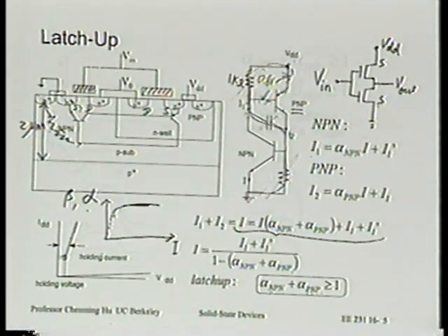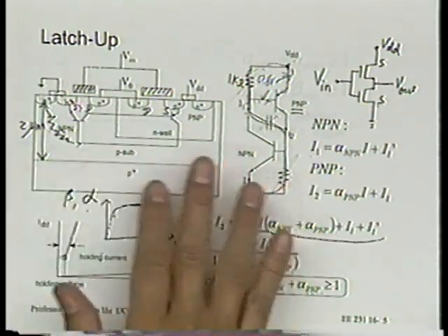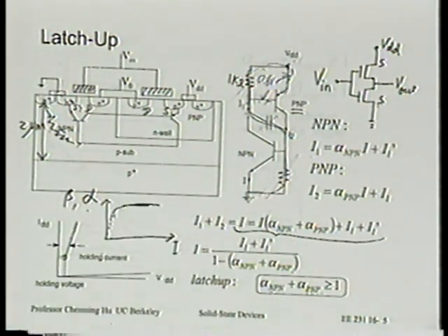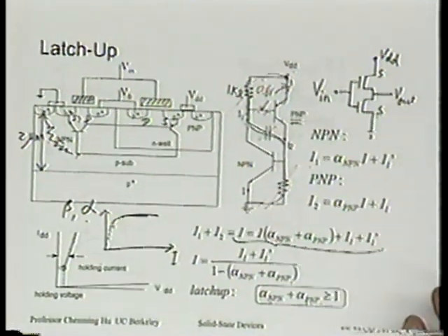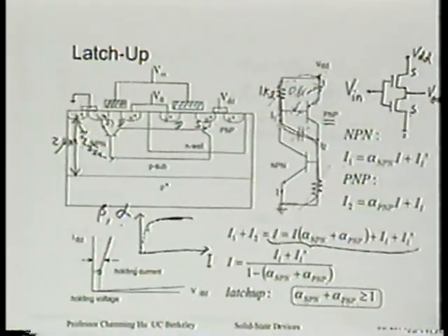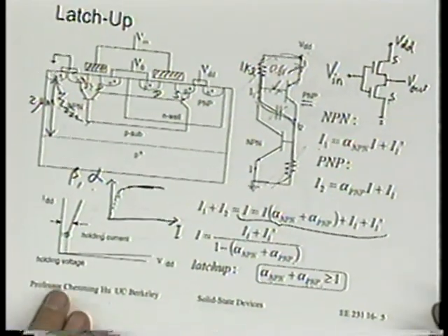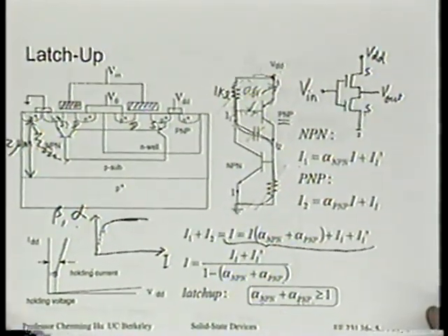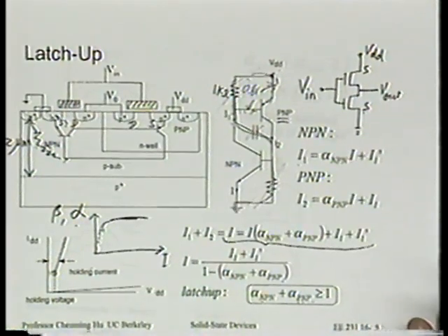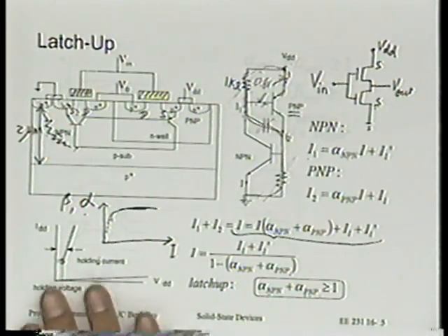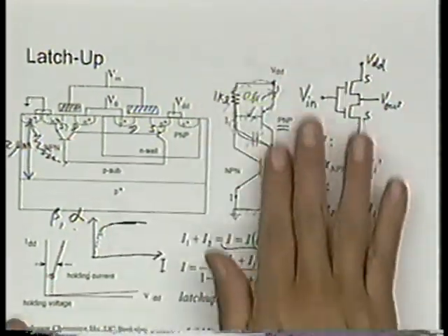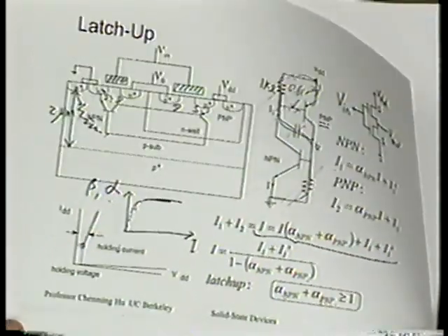Is that right? It has been very difficult to do that unless you do something really fancy like a buried layer, N plus, and P plus layer. But with power supply voltage dropping, that becomes somewhat more realistic. So it's certainly worthwhile to start thinking about what controls this holding voltage, what's the theory behind that, and how can we increase it and make it even larger than VDD. By the way, you can analyze the holding voltage and holding current using this equivalent circuit. All right? Okay.